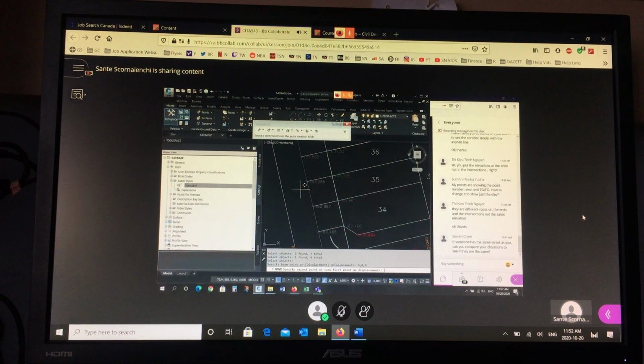I'm not going to move them in the northing, so 0, comma. I'm not going to move them in the easting, so 0. Keep them at the origin so that they don't move in the plane. But I'm going to add 0.3 to the vertical. So I'm taking it from 0, 0, 0 straight up to 0, 0, 0.3. 1 foot higher, 0.3 higher. Watch the numbers when I hit enter.